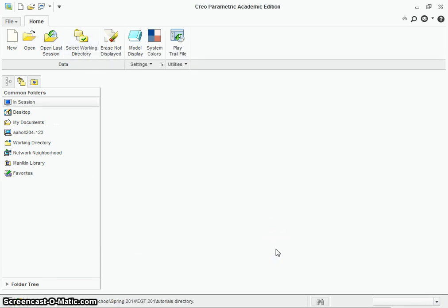This is important to do because it actually has everything save automatically to one folder, and that's important because if you're working in assemblies and stuff like that, Creo actually has the ability to change features that are tied to other components and stuff. And it just needs to be able to have everything in the same folder so it knows where to actually look for stuff, and that way Creo doesn't give you any type of errors or anything.